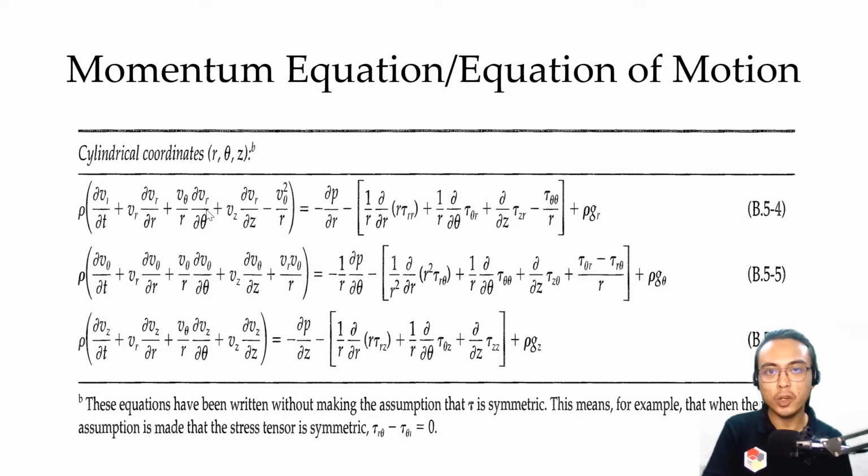We have established earlier that for unidirectional flow, we don't have a radial component of velocity, meaning this is just 0, 0, 0, and 0. So the entire left-hand side of the equation is just 0. If you take a look at the right-hand side of the equation, we are only interested for the shear stress acting on the z direction, varying on the r direction, and that is not what is written here.